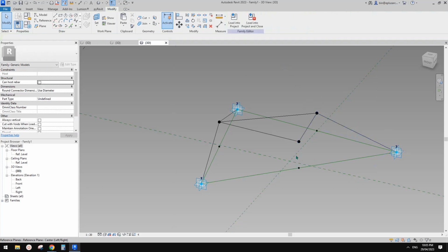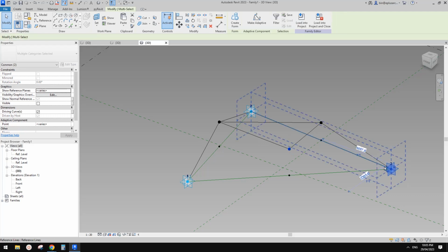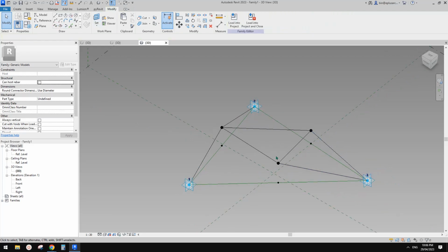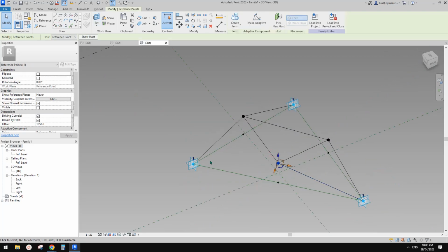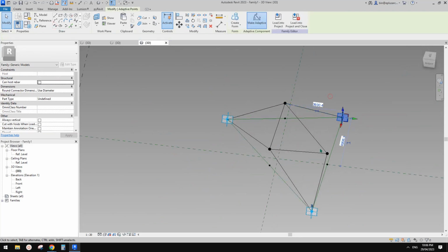And this point, and you notice that this is a little plus, so I pressed the Control key. So you use the Control key to add elements into your selection. So select these 2 points and use spline through points to create a line. Okay, and then 1 and this point, and 2 and this point.